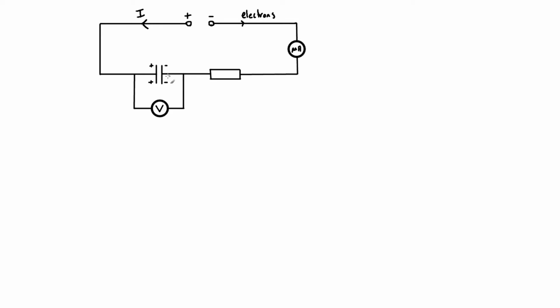As the capacitor begins to charge, okay, one plate becomes negatively charged, the other plate becomes positively charged, what we will see then is the potential difference across the capacitor will increase from 0, and we will start to acquire a reading on the voltmeter. And of course that also means the reading on the potential difference across the resistor here would actually be decreasing. And what that means, of course, if we've got less volts across the resistor, less current is going to be passing through the resistor. And you can see why that would really be, because of course as we start to acquire